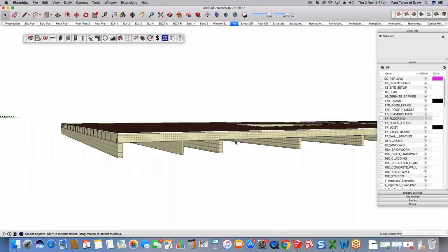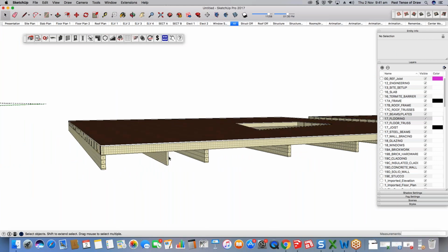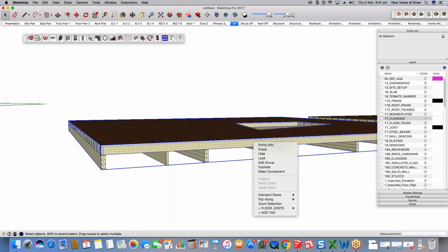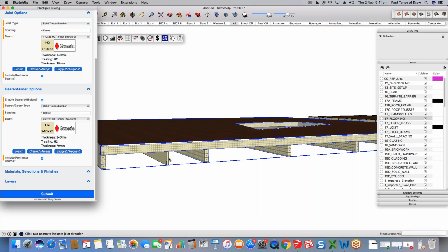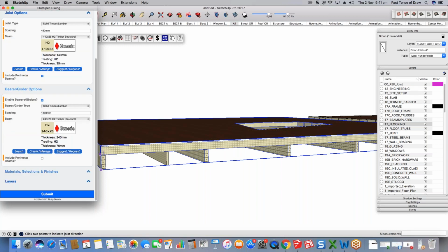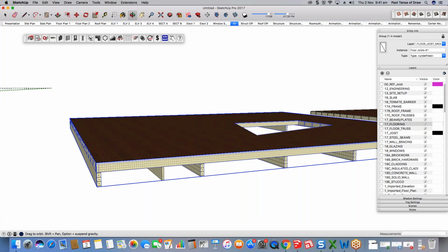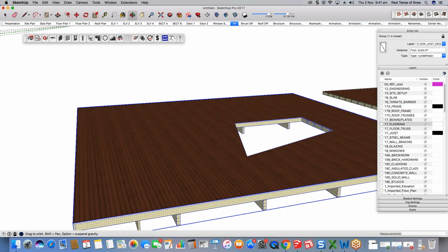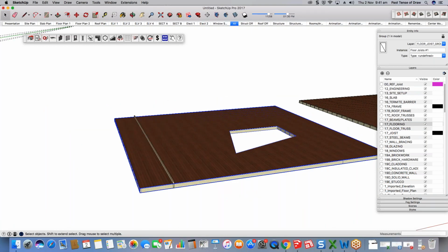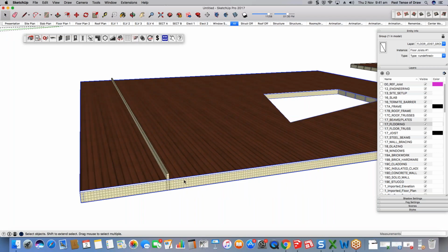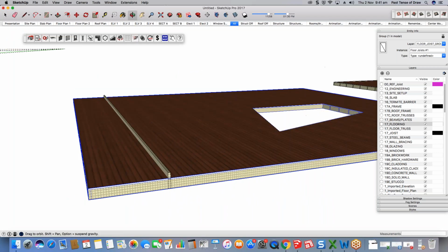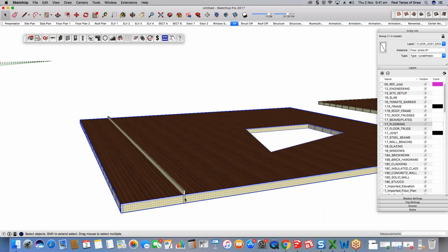If you're going to go to an extremely high level of detail and you've got very custom placements, etc., it might be better to simply, for your bearers, for example, not generate them with PlusSpec. So again, I can actually just go back and untick them and instead just use the beam tool to manually put in each element. So I'm going to untick it, press submit. And again, you need to tell it which way it's spanning each time that you make a change. You can lower it. It depends on how you told it or where you told it you want it to be generated from.